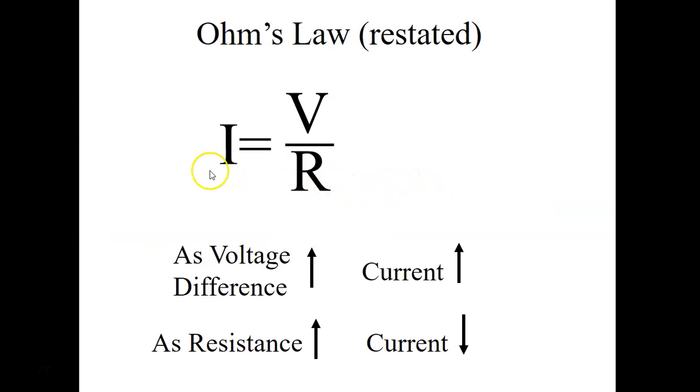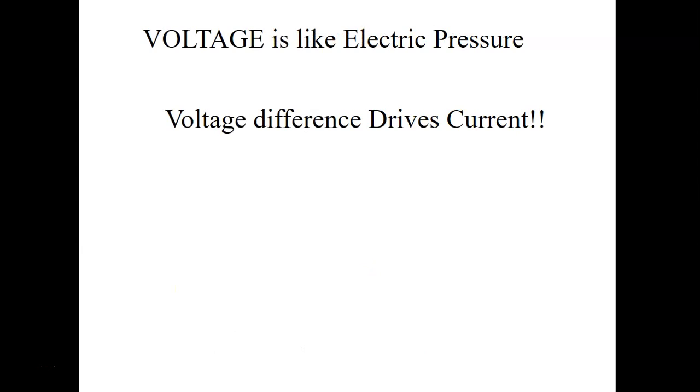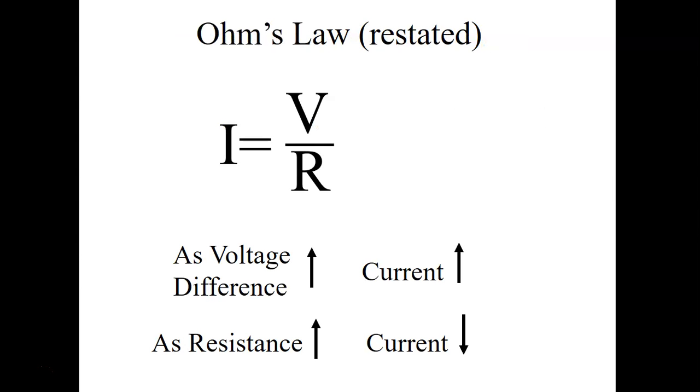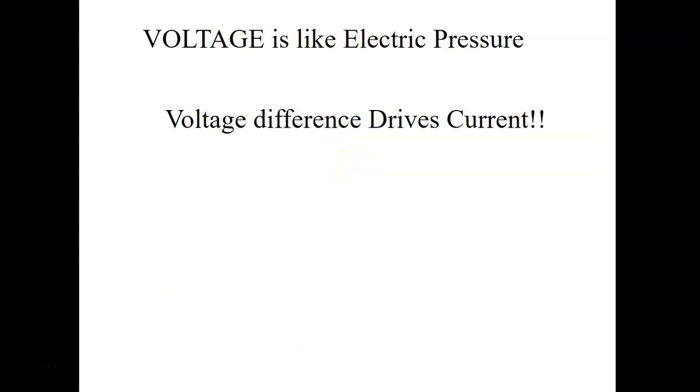If we solve this for I, or current, what this tells me is that if I increase the number on top over here, if I increase the voltage, then this side will get bigger. In other words, more voltage means more current. It also means if I make this number bigger, I'm going to make this side of the equation smaller, and therefore this side of the equation smaller. So if I increase resistance, I decrease current, which we already knew. And that's known as Ohm's law. But it reiterates that for us, so it makes sense.